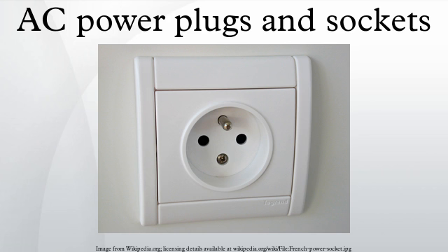There are several AS/NZS 3112 plug variants, including ones with larger or differently shaped pins used for devices drawing 15, 20, 25 and 32A. These sockets accept plugs of equal or lower current capacity, but not of higher capacity. For example, a 10A plug will fit all sockets, but a 20A plug will fit only 20, 25 and 32A sockets.